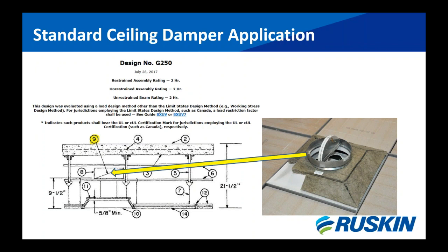So that was basically an original design for a radiation damper. So to the right, our current design was tested against the hinge door and proved to be equal in performance. So any of these designs that have the hinge door can utilize a current ceiling fire damper, and that's industry-wide.